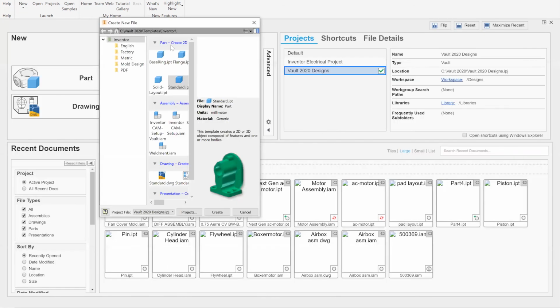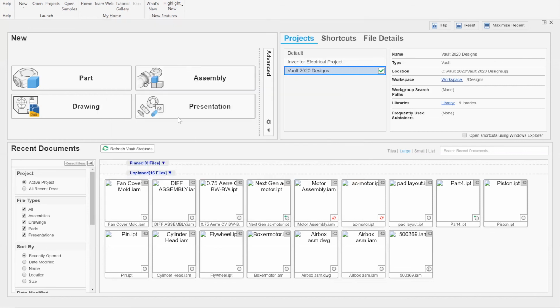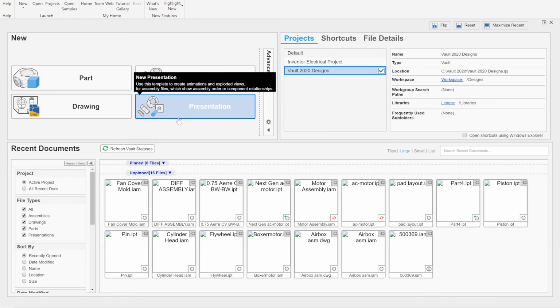What that means is that we're not actually translating that SolidWorks file into Inventor parts and assemblies. So if you bring that in as a reference through the AnyCAD technology, and that SolidWorks part or assembly changes, those changes and updates will be reflected. I like to think of it as kind of like object linking and embedding that actually works. It's not really the same technology, but it's the easiest way to explain it.